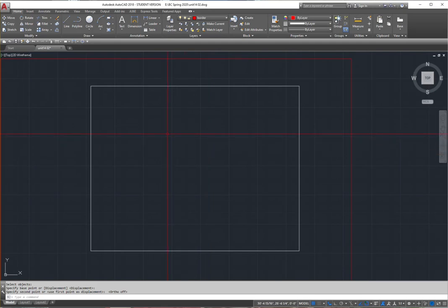Now you'll say, why do you use single lines? Well, I could have created a rectangular box and then I would have to explode it because I have to offset it. And remember, when we offset, we're making a copy of the object if you want. Your instructions say, because we're recreating the classroom, you're gonna have wall thicknesses, and in this case